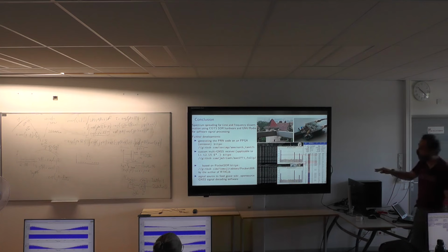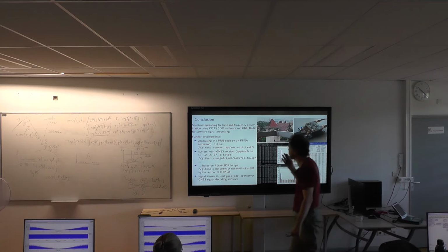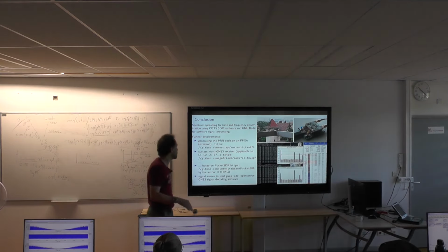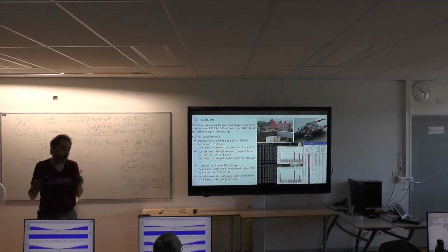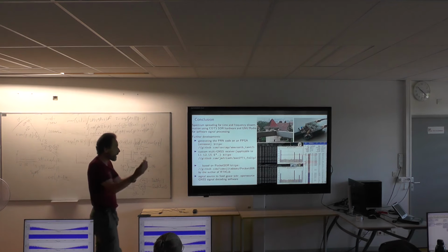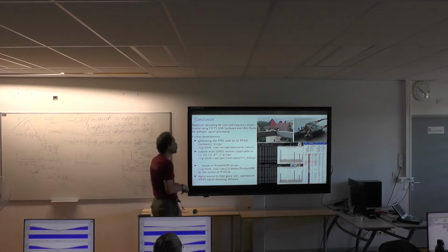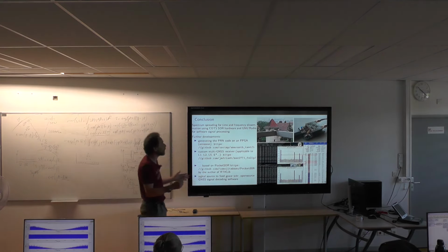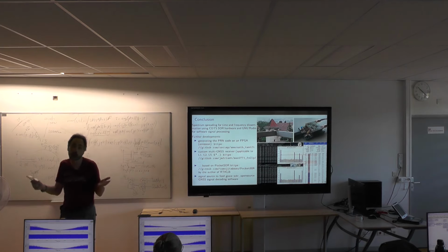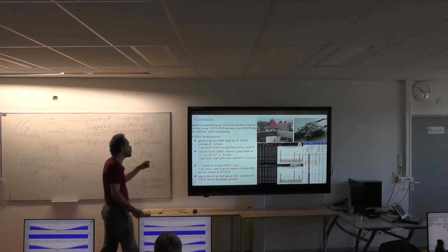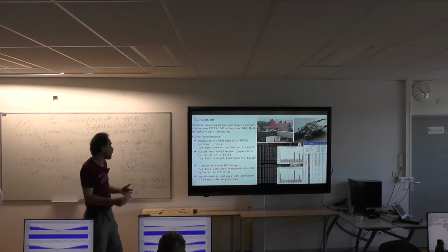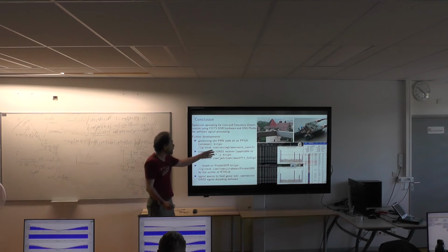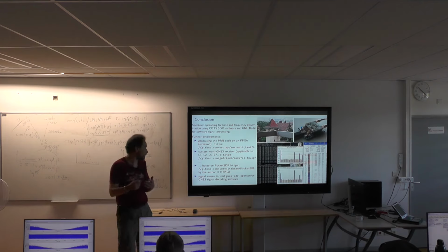I wanted to show you how spectrum spreading is at the core of time transfer and time and frequency dissemination. I wanted to show you that using a commercial off-the-shelf software-defined radio, you can actually process from the very bottom, from the very IQ stream, using GNU Radio, the data that we collected. There's a lot of things you can do additionally. You can have a look at the software we wrote for generating pseudo-random sequences on FPGAs.